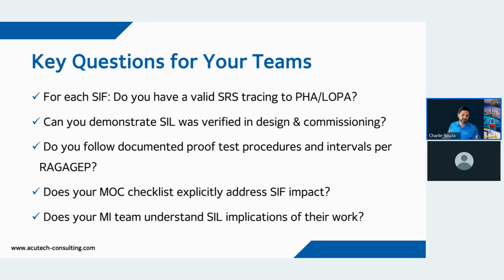So have you done your 5-year revalidation, found some issues, made some changes, but never thought about going to the functional safety side of things and checking that documentation to make sure that you don't need to revalidate those as well? Can you demonstrate SIL was verified in design and commissioning? Do you follow documented proof test procedures and intervals for RAGAGEP, or do you just bundle that all into maintenance